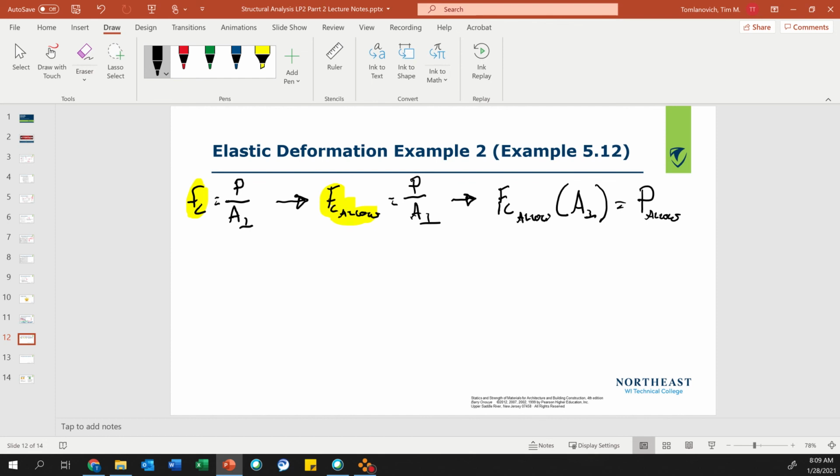So basically what we do is calculate the actual stress on that member based on your load tracing and your dimensions of your structure, and then you're checking it against factors of safety and allowable. So this is typically how you would design it. I want to use a Doug fir column. This is the area that I can use, right? This is a remodeling project, and does my existing load exceed that allowable load? So you're checking it back and forth, so you can rearrange that equation.